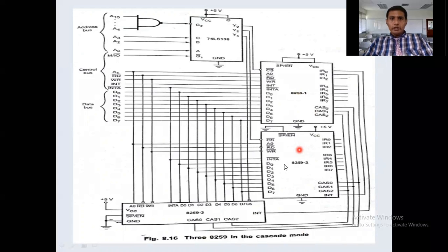Here also we are taking the 74LS138 as the address decoder, and here also G1 bar, G2 bar and G. Just for a change, G is now connected to VCC, nothing but the power supply pin. Okay, then G is activating. G1 bar is connected to M by IO bar. So in order to activate, IO bar should be 0. 0 is given to G1 bar, then G1 bar is activating. So in which way are we activating G2?